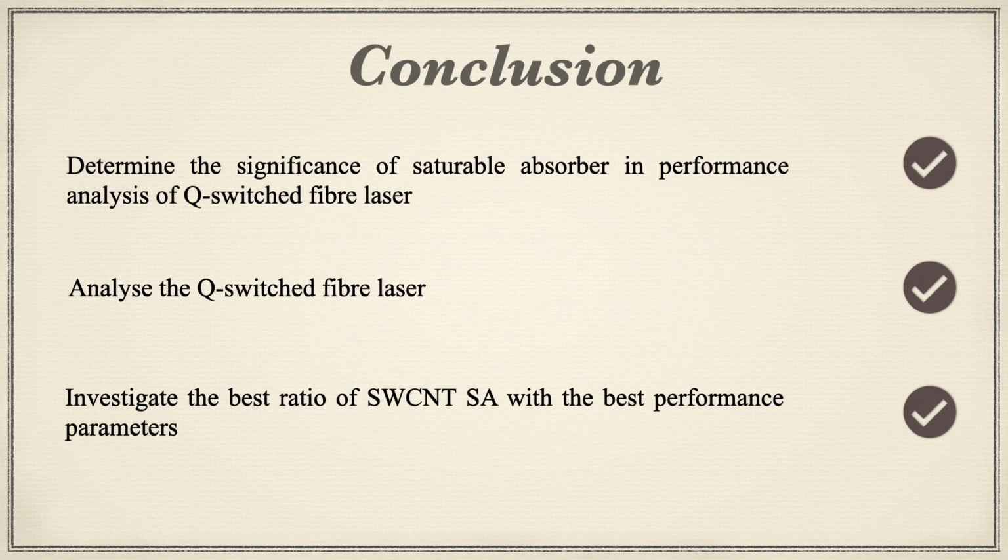is achieved, as the Q-switching EDFL system shows forward-shifting output spectra, although with different ratios of SWCNT-PVA saturable absorber, proving that the presence of the saturable absorber speeds up the self-starting of the Q-switching. The purpose of parameter analysis and the investigation of the best SWCNT-PVA saturable absorber ratio for the passively Q-switched fiber laser has been fulfilled, and the SWCNT-PVA of ratio 2:3 is the best as it achieves the highest maximum pulse energy and the highest output power with short pulse width.